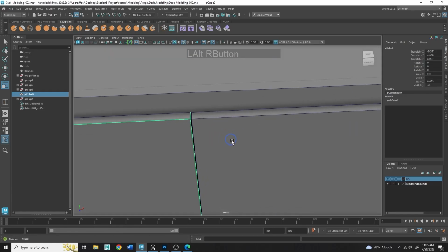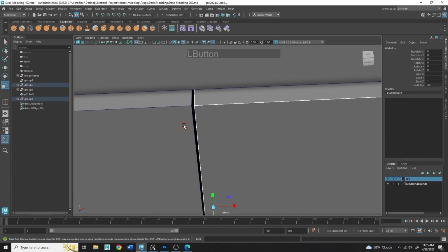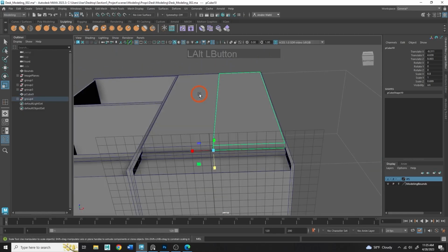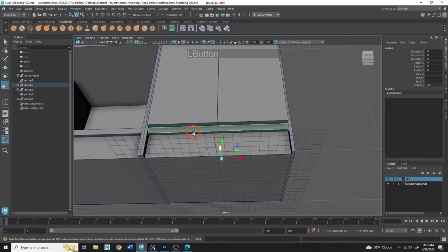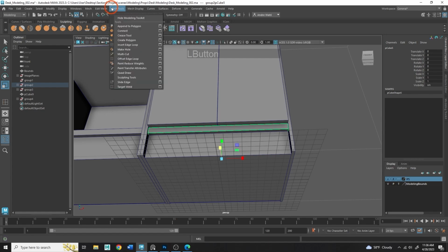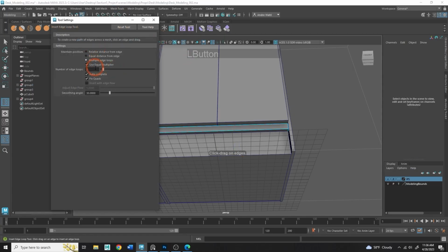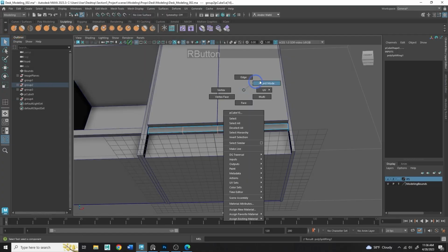And hopefully not overlapping. You can see they are, however, touching a little bit, which is unfortunate. We do want this to be perfectly symmetrical. So what are some solutions we can do for that? There's a couple of different solutions. One of the ones I already showed you is to get a line you can snap to using insert edge loops. So for example, I could take this edge here. We could go to mesh, insert edge loop here, set this to multi-edges in 3, and just click on this to get the midpoint of where this needs to snap.